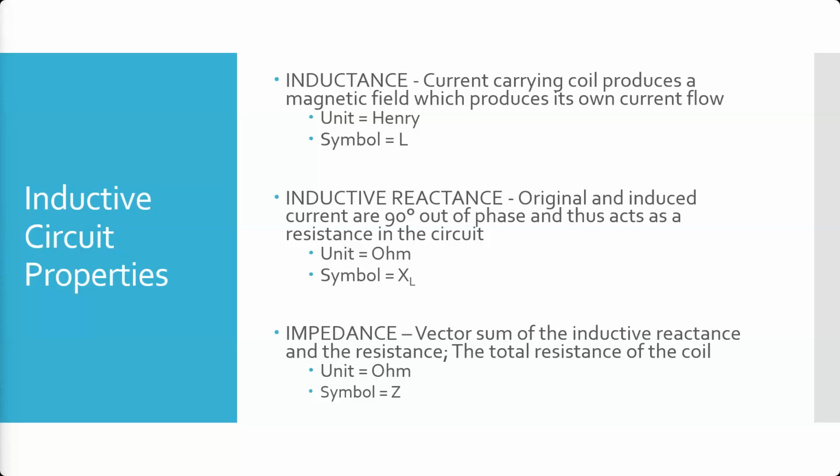Both of these, inductance and inductive reactance, are affected by conductive materials, not necessarily magnetic, but conductive materials that are in proximity to the coil.